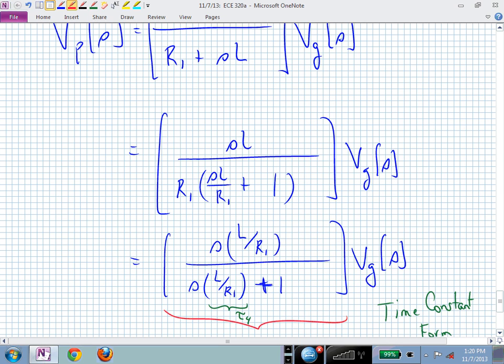But now, that was a 0 in the numerator, which allowed us to build up from nothing and go up. That's what it's doing. But eventually, this denominator is going to get bigger than 1, isn't it? When I get frequencies large enough. What's my break frequency in the denominator? That's R over L, isn't it? That's my break frequency. So at R over L, my denominator's real part and imaginary part are equal. That's where I need to start worrying about the denominator. But until that point, my numerator is just climbing up. It's climbing up from really far down, 0, which in dB we never reach, do we? We just keep coming up from minus, minus, minus dB. And then at the break frequency, we level off.